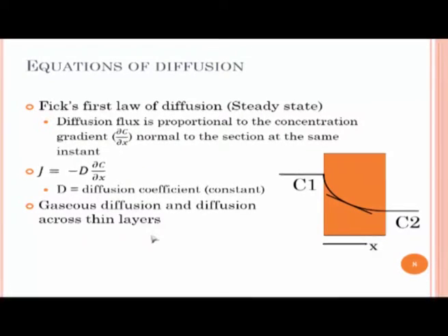For example, when you test concrete at 7 days, it is going to be different from concrete that is tested at 28 days. Why? Because during this time you provided more chance for reactions to happen and structure to develop further, okay. So because of that, such a system which talks about steady state flux of the ionic material from one end to the other will not be applicable to something like concrete. So what should we do for that? For example, if you are talking about chloride diffusion in concrete, you simply cannot adopt this approach because your system, the concrete system, is constantly changing. In other words, if you really look at it, this diffusion coefficient D is not a constant in the case of concrete, it is continuously varying.